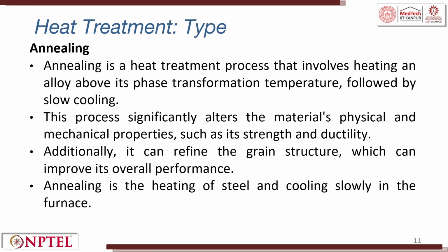Annealing. Annealing is a heat treatment process that involves heating an alloy above its phase transformation temperature, where there is a change of phases, right, followed by slow cooling. The process significantly alters the mechanical properties, such as strength and ductility, of any given material.